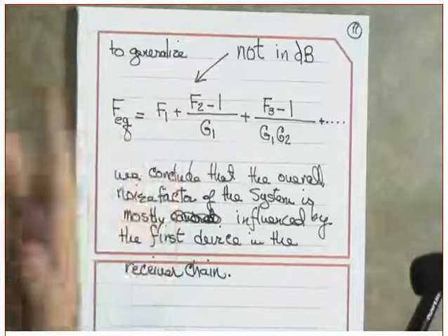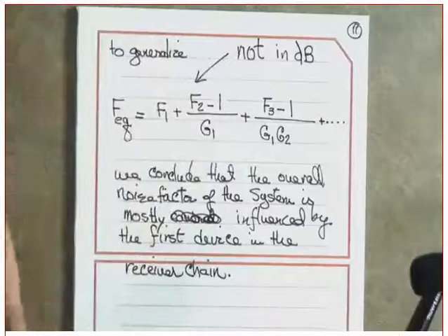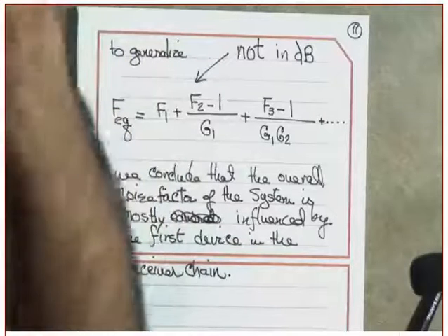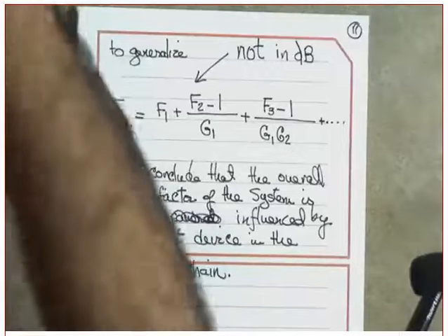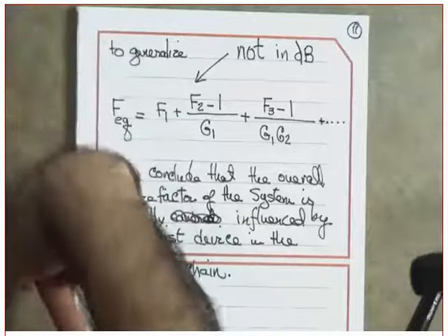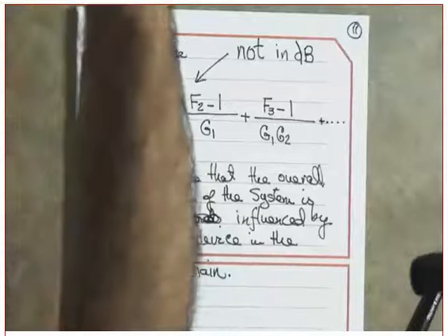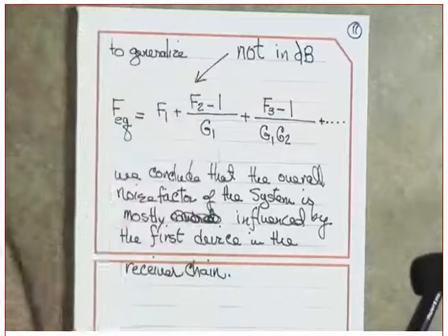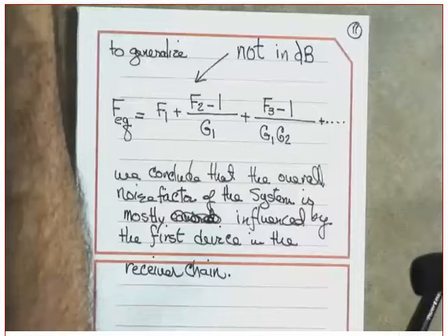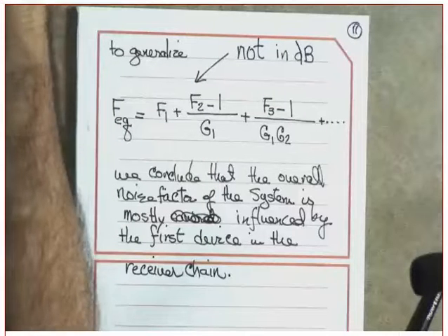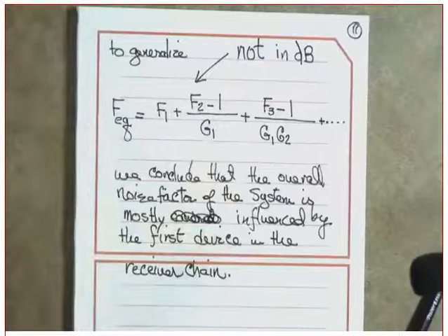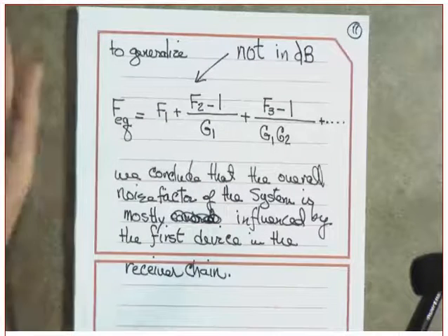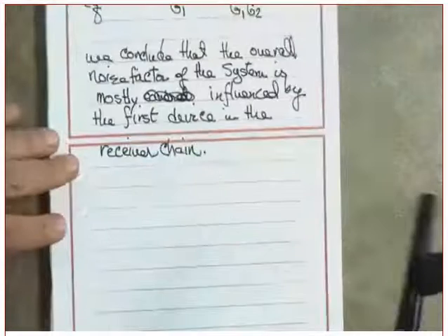Extend cable. Let's assume your receiver is indoors, but the antenna is outdoor. So you are going to extend the cable from the antenna to the receiver inside. That transmission line, we just saw that it will introduce some losses. And when it introduces some losses, it will also introduce degradation in the noise factor. Clear? So you need to look at this carefully.